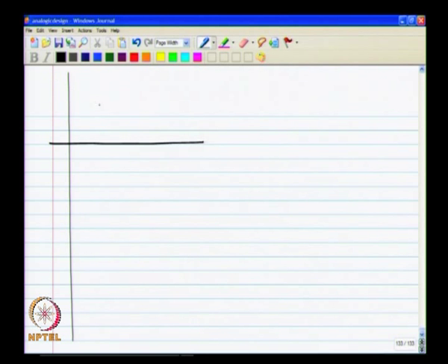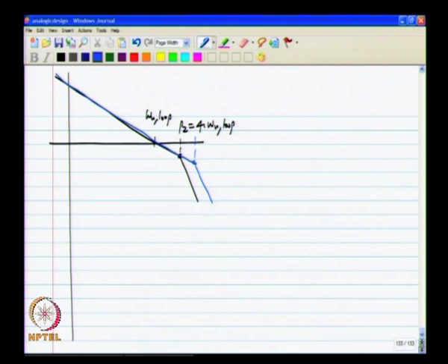So, if you have a second order system, for critical damping, the second pole should be at 4 times the unity loop gain frequency, and if you have 2 identical poles, they should be at 8 times the unity loop gain frequency.